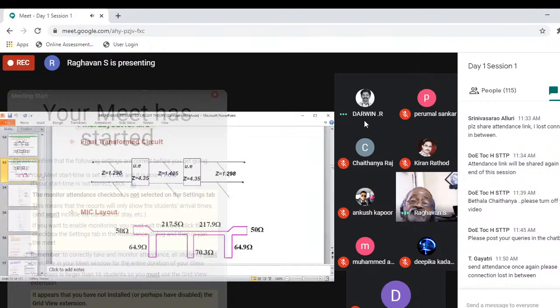just like different versions. So now you can see, the highest ohms has got the least width, and the least, 50 ohms, has got the highest width. And once you get the impedance, make use of Wheeler's curve and then get the width.